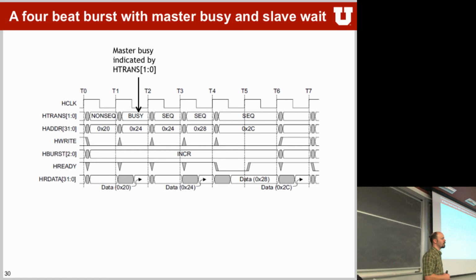Yeah, you can do optimizations in your peripheral. For example, if we know the size of our read, we could go and get bigger chunks out of flash memory. Or if you have to access an external bus system, we can go and get bigger chunks from there to optimize the bus transfers. And that's all what bursts are actually used for. And there are a lot of different bursts.